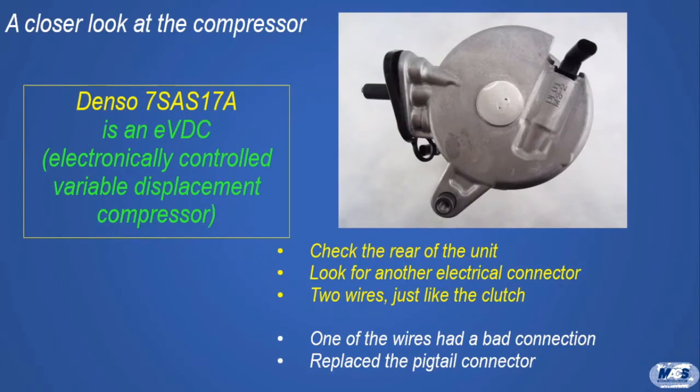The technician ran the jumper to the coil once more, and any pumping by the compressor was minimal at most, and he was ready to install another compressor. But he disconnected the jumper and turned on the AC via the dashboard controls. This time the compressor pumped. What's happening here?